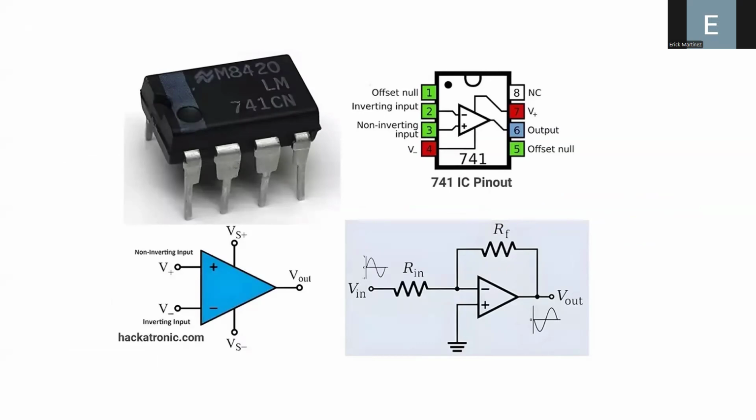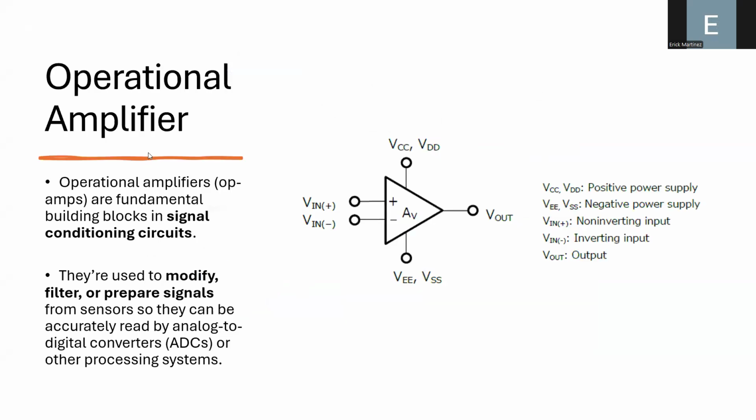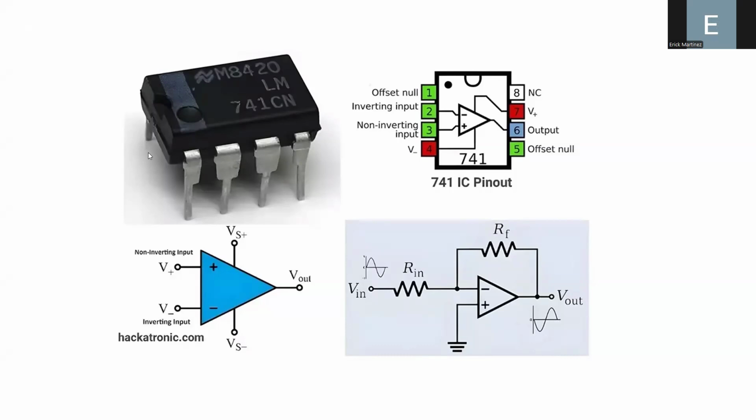And this is a schematic or a photo of the operational amplifier. This is one of the most common ones, the 741. And here I'm showing you the schematic of this electronic component. Typically, this device has 8 pins. But the important part here is that the schematic tells you about the connections, okay? There is a relationship between this triangle and the connections that you are seeing here. For example, 7 and 4 are the pins in which you need to power the device.